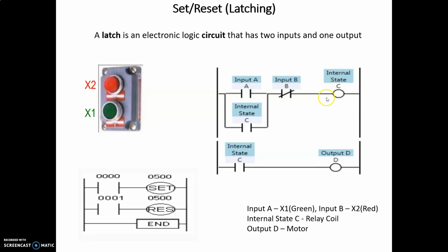Now as soon as the C coil is energized, internally this connection is there in between this part here. Look at the C symbol, both of them are the same. So when this becomes energized, it will try to energize this part also. That's why the push button helps here. So now let's come back to the initial part again.